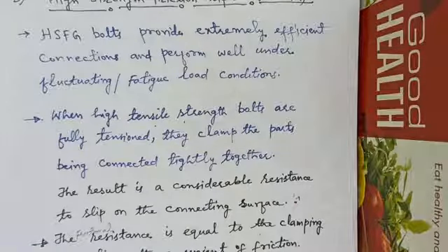Normally, for ordinary bolted joints, the force is transferred through the interlocking and bearing of the bolts. However, for high strength bolted joints, this transfer of force is accomplished through the friction between the interfaces formed between the load carrying elements joined together.